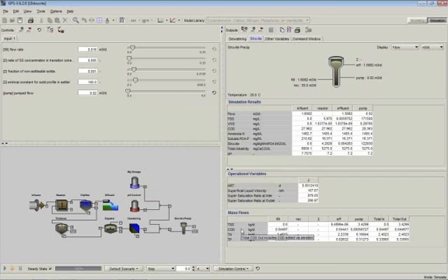You can define the characteristics of the bed, so that will tell you how much solid separation you're getting. And so we can see here, for example, with a small amount of flow being taken off the bottom of this reactor, we have quite a large concentration of struvite coming out because we've precipitated it out. We've concentrated those solids, and we're getting about, from this table down here, almost 3.5 kilograms a day of struvite removal for this fairly small reactor.